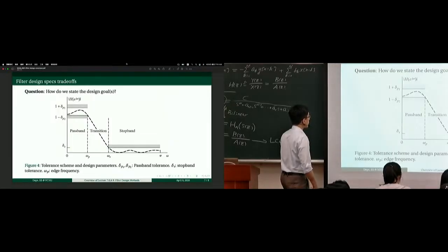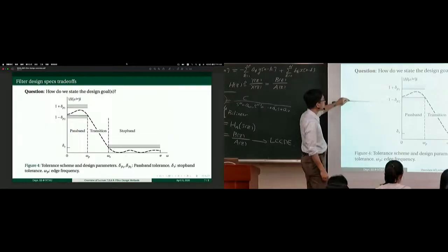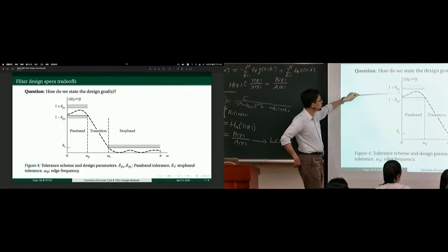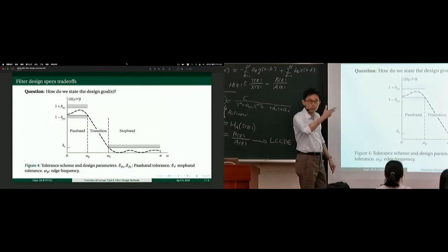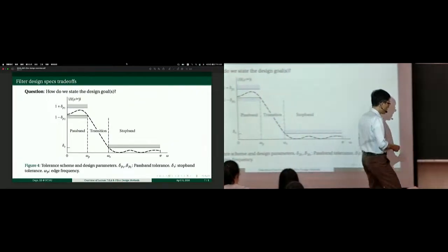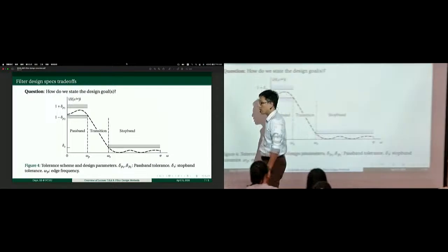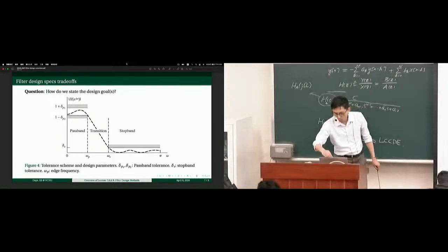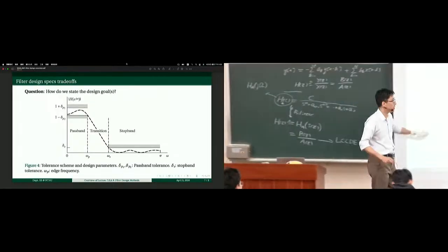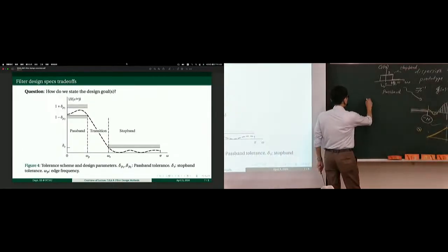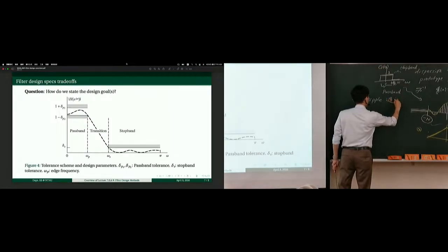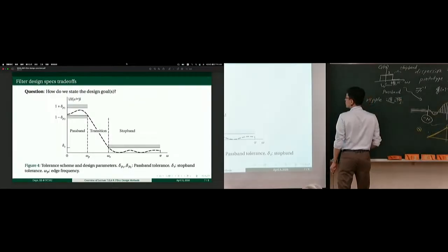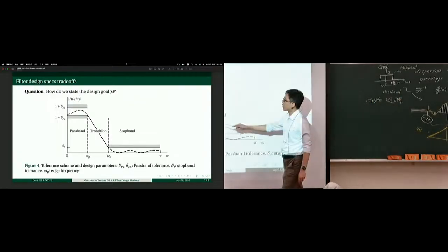Usually we'll be looking at several examples. Usually within the pass band, we can tolerate some error. Ideally, we want the gain to be 1. But we can tolerate some ripple, so to speak, ripple, 涟漪. Ripple is when you drop a rock in the lake, the kind of small wavelets that it's making is called ripples. Ripple. So we can tolerate some fluctuations within passband.